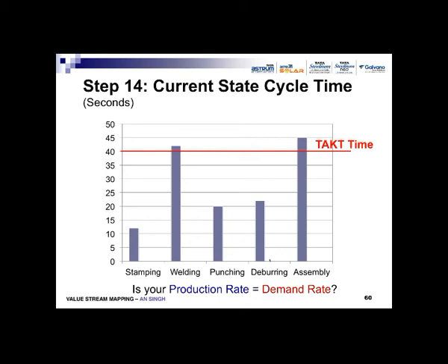If you are continuously producing with the low cycle time, you are piling up inventory. But at the same time, if your cycle time is more, then it means that you are not able to meet the requirement of the customer. So whatever goes above the takt time has to be brought below the takt time level. How can you do it? By making Kaizen, by making improvement in the process, improvement in the operation, improvement in the technology.